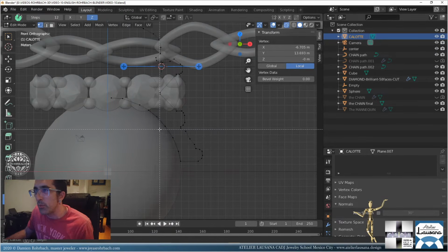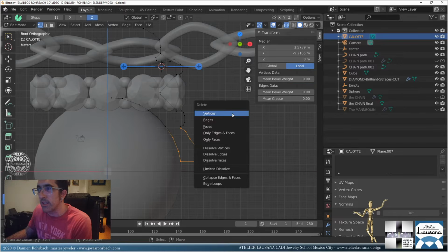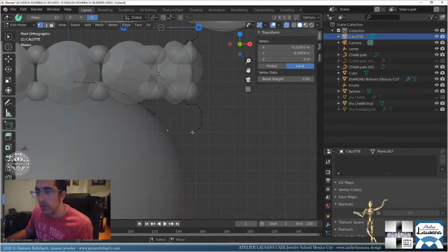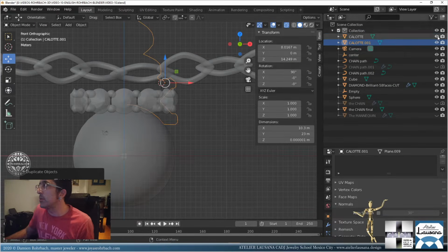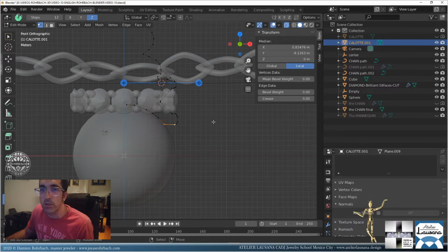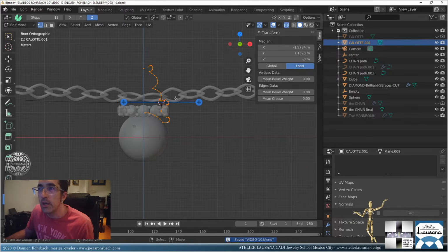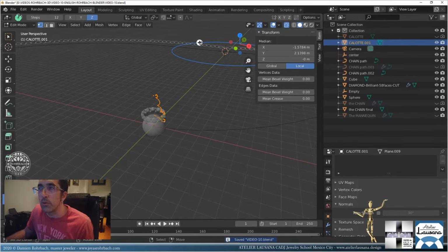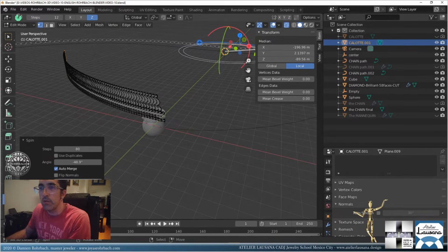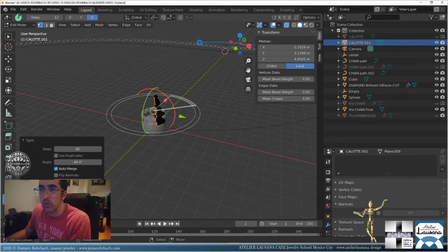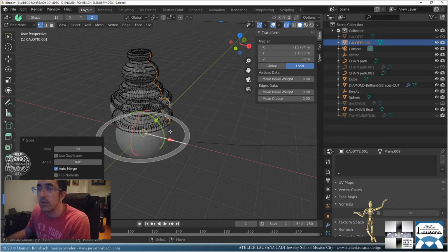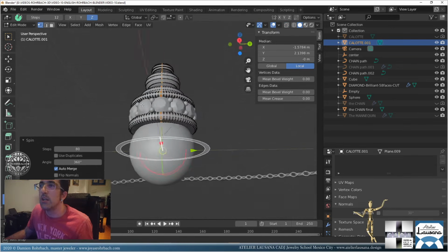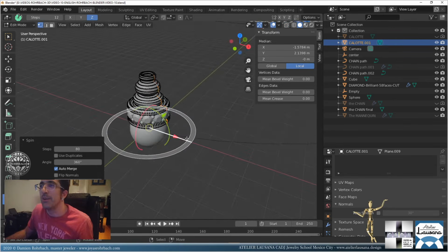So basically we're going to remove this section here. Poof. It's better at the top. Okay, this is good. This should be better. Now shift D, enter, hide the original, edit mode. Okay, a spin. The cursor is way wrong. Center there, 360 degrees, 80. That's better.